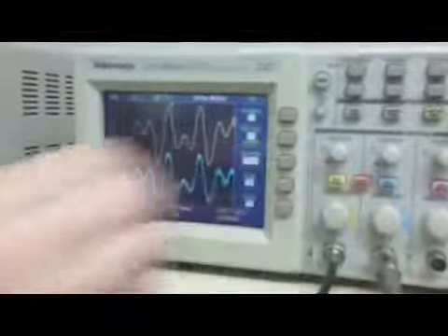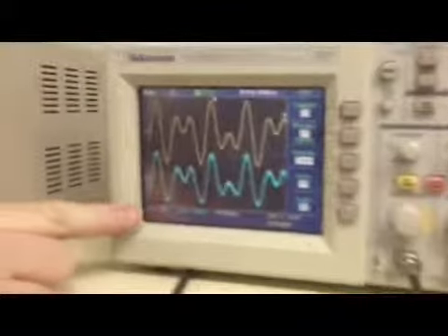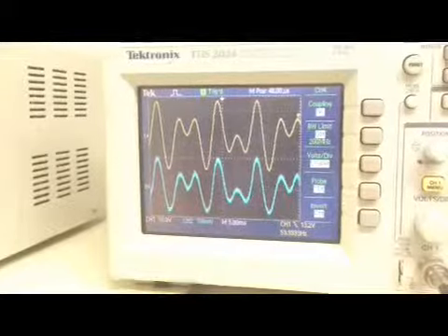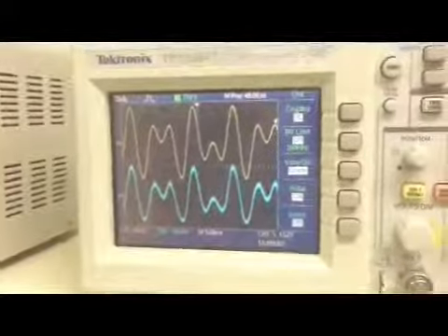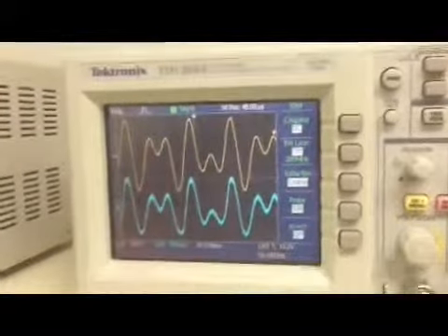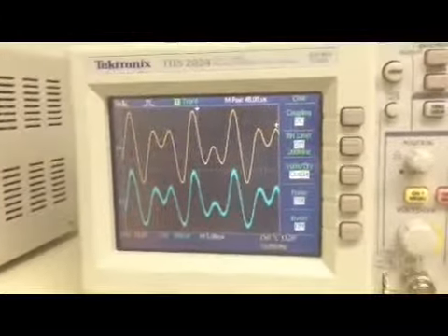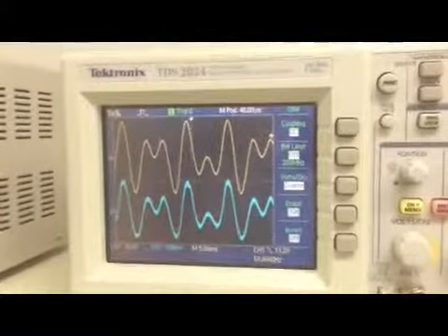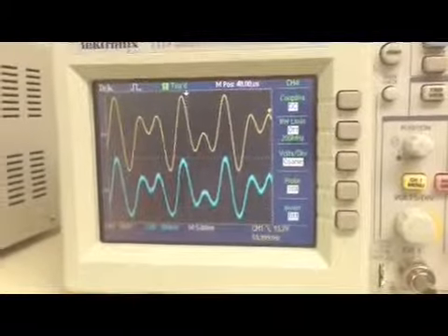You can see up here that we have our glide slope signal coming in and the glide slope signal from the receiver board. It does have a bit more noise because we're missing about 40 dB of gain and an attenuator stage out of the receiver due to the fact that we don't really need that much gain. We only have to receive down to minus 79 dBm for the FAA specifications.